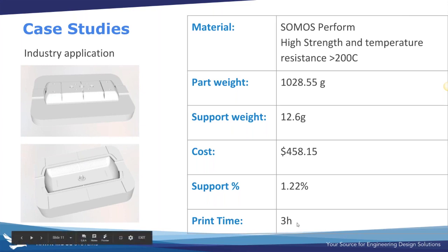And it didn't take that long to print either. It was only about 3 hours to print. If you needed to make another design change, this is how you could find that there's an error in your design way before you go to a real injection mold.